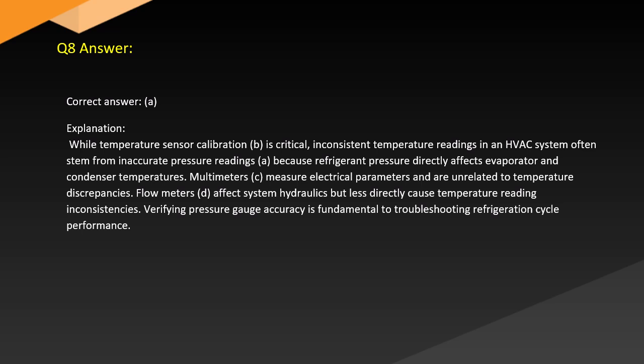Answer. Correct answer: A. Explanation. While temperature sensor calibration, B, is critical, inconsistent temperature readings in an HVAC system often stem from inaccurate pressure readings, A, because refrigerant pressure directly affects evaporator and condenser temperatures.